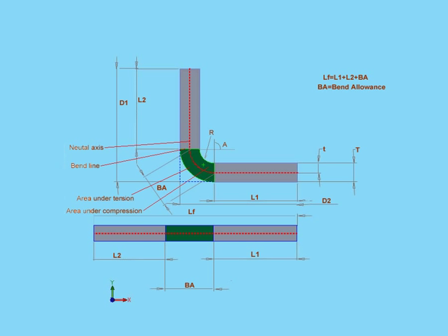You need a piece of the exact same sheet metal you're using to manufacture your part, and then you'd bend it using the exact processes that you'll be using during your machining. Just take some measurements before and after the bending, and then based on this information, you can adjust the bend allowance as needed. Another method that SolidWorks uses is the bend deduction method.